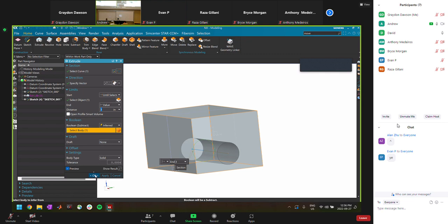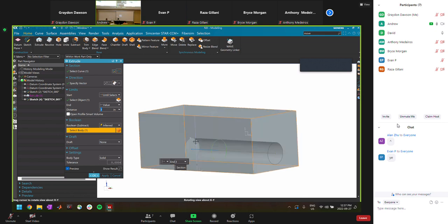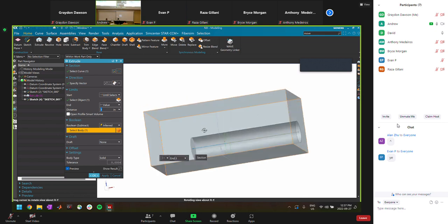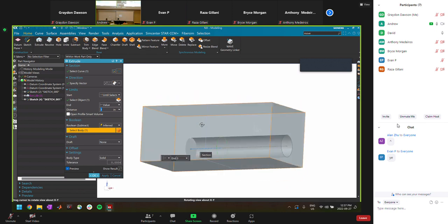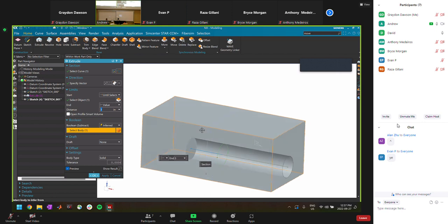Rowan, I would say just for style, I personally find that instead of offsetting on either side, so that the part doesn't break when you change that length, if you go to until face, it makes it a cleaner part. Or you can do until max, or until the base, so that when you change dimensions, it doesn't explode. That's for people who maybe aren't super comfortable with it, when they are making actual parts.